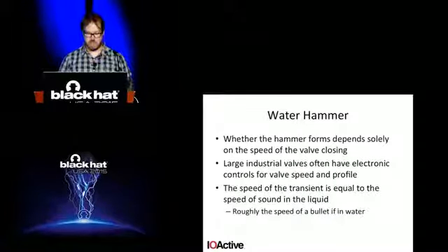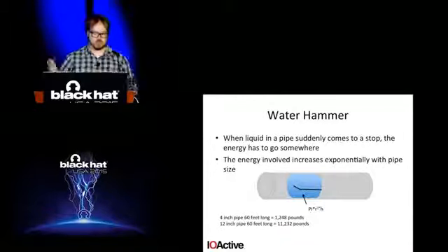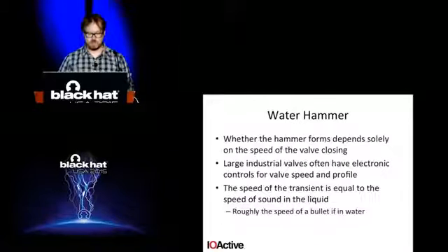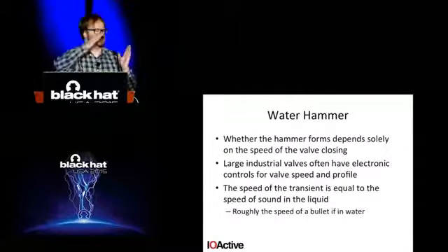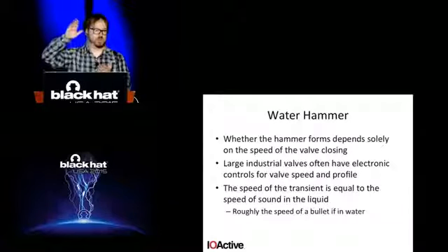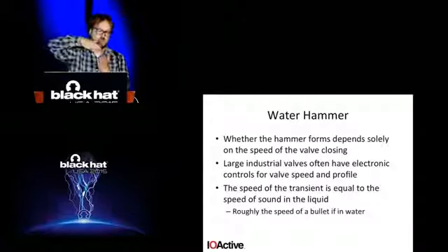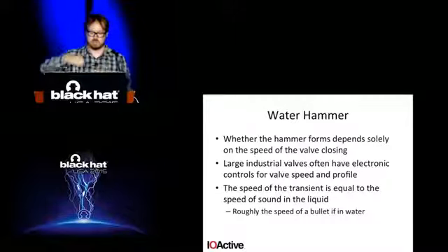Whether or not the shock wave forms actually depends on the very last closing part of the valve. As the valve's closing, it can close really fast, and it's only when the valve actually touches the seal that the water hammer forms. We did a bunch of experiments with this, and you never quite know what the weakest link is going to be.